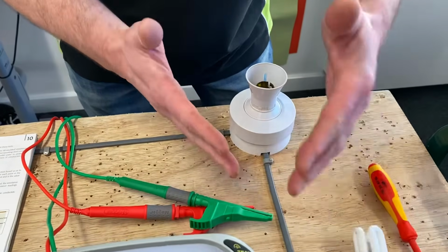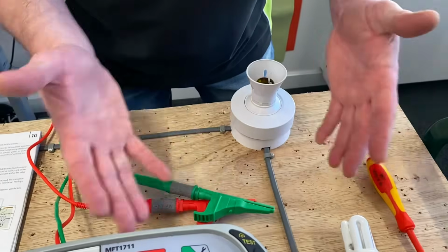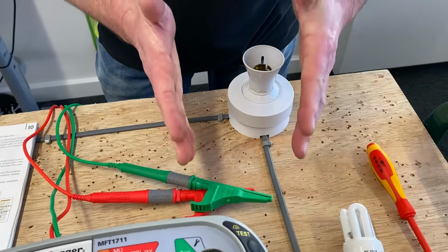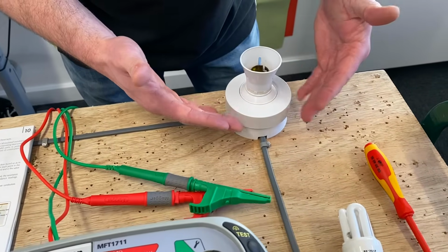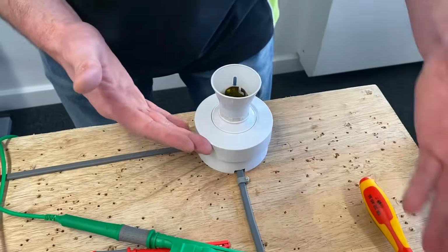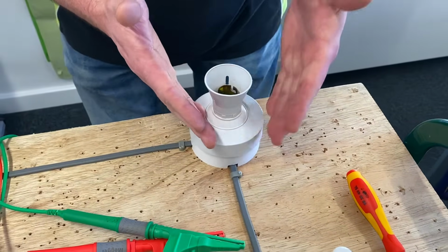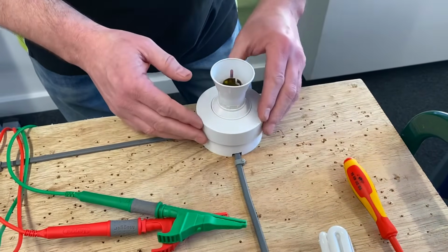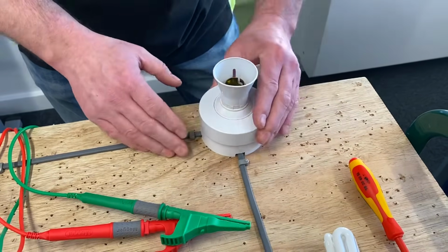In the real world, if there are 10 lighting points on a circuit, so maybe 4 bedrooms, a landing area, an upstairs bathroom, etc., you'd need to do this test at every single lighting point and switch. But in a college setting this time round, we've only got one lighting point and one switch, so we need to prove the CPC gets to here and the CPC gets to the switching circuit. But if there was more than one, you'd have to continue the test for all of the points on the circuit and record the highest reading.